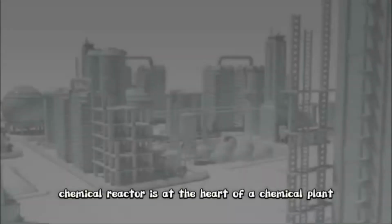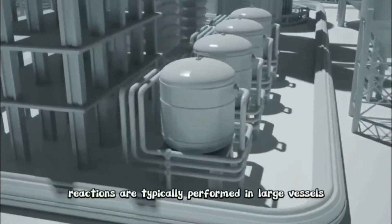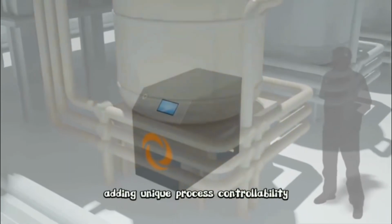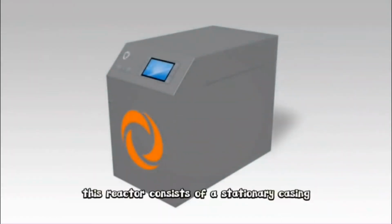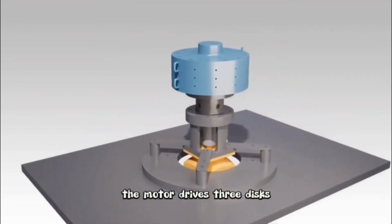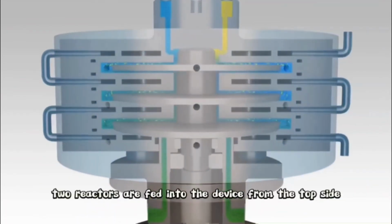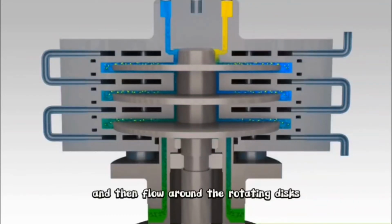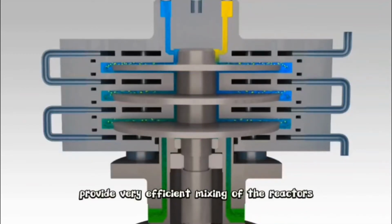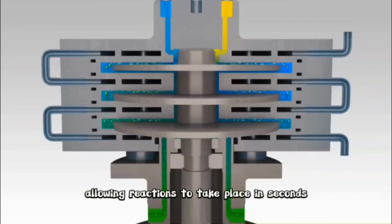Please enjoy. Chemical reactor is at the heart of a chemical plant. Reactions are typically performed in large vessels. The spinning disc reactor outperforms conventional reactor equipment, adding unique process controllability. This reactor consists of a stationary casing connected to a motor. The motor drives 3 discs, which rotate at high velocities inside the narrow casing. 2 reactants are fed into the device from the top side and then flow around the rotating discs. The large shear forces provide very efficient mixing of the reactants. This results in high mass transfer rates, allowing reactions to take place in seconds.